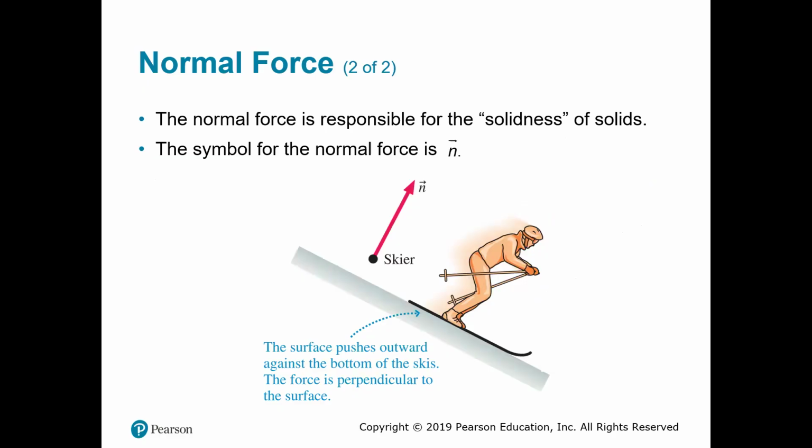Okay? And then for example, again, this is an important example. You see the normal force, one very common mistake is that students assume the normal force is always straight up. No. Again, the normal force direction is always perpendicular to the surface. So if you have a ramp like that, your normal force is perpendicular to this surface, not always straight up.